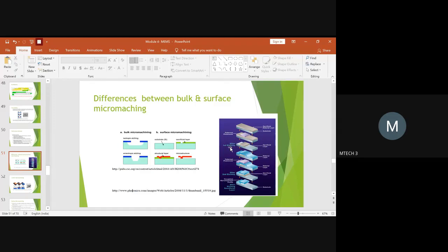So this is the first etching. When you etch out, this pattern will be retained and the sacrificial layer will be removed at this end as well as this end. So you can see in the third diagram, the sacrificial layer is retained only across the pattern which was there before, right? The remaining amount of the sacrificial layer is removed, and hence the name sacrificial layer.